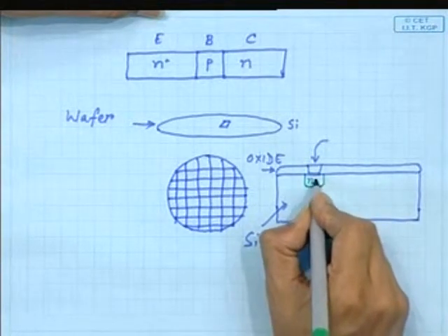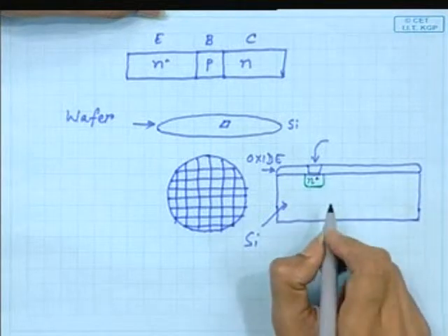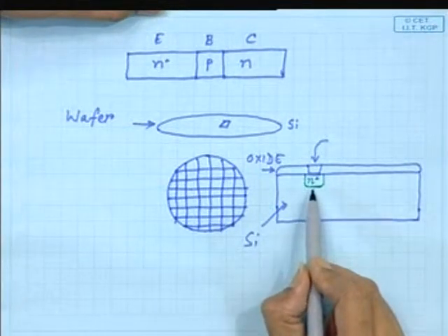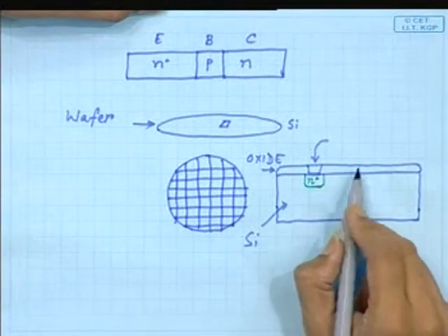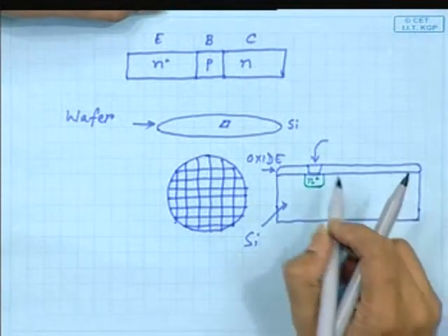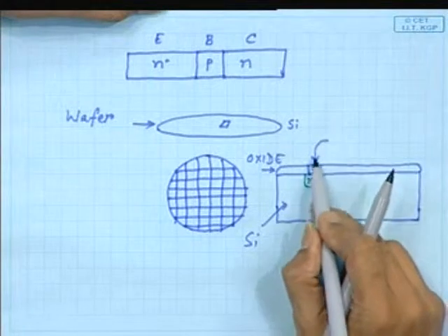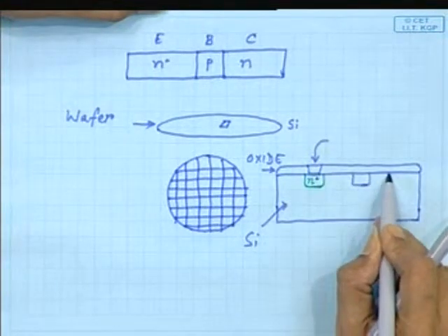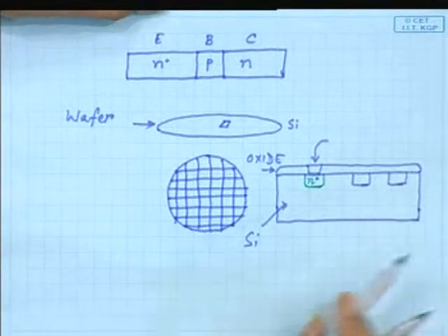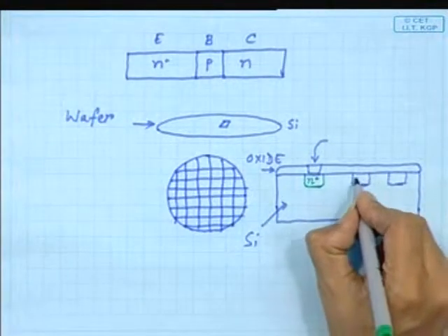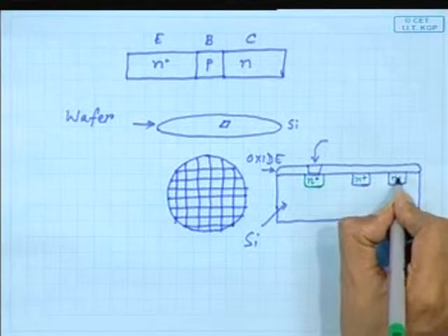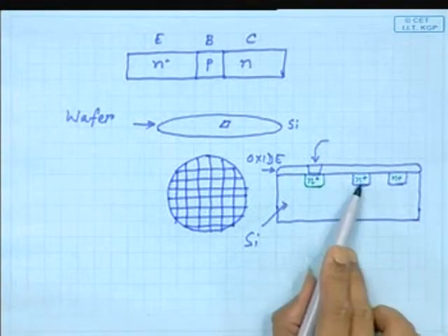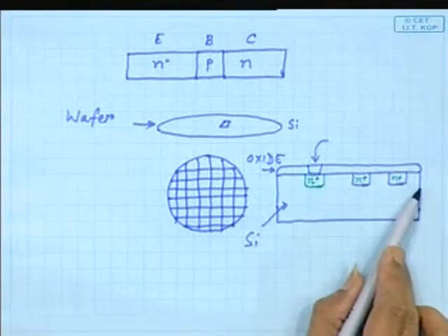Okay. Now, depending on the doping concentration, the time and temperature, you can determine the depth of the junction. Similarly, if you open windows simultaneously while you are exposing to N type dopant, you can have many such N islands. So, in your design, suppose there are millions of transistors, in one go you can have millions of such islands made.